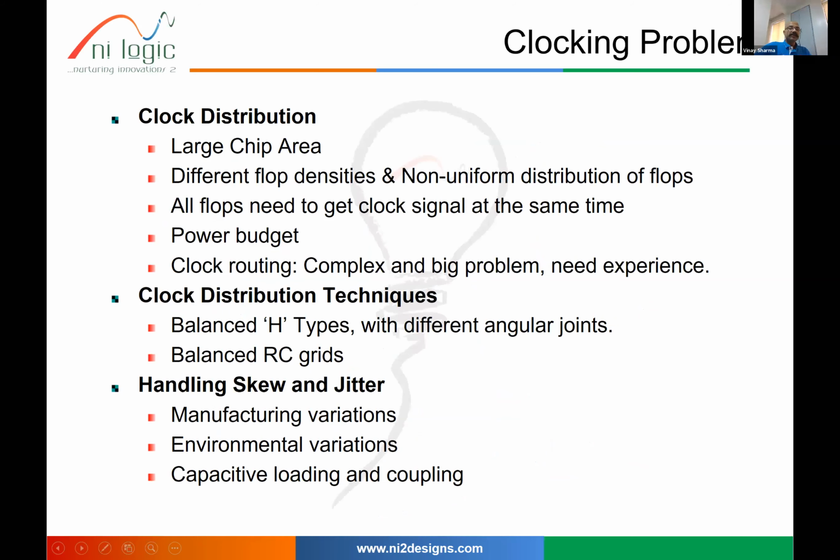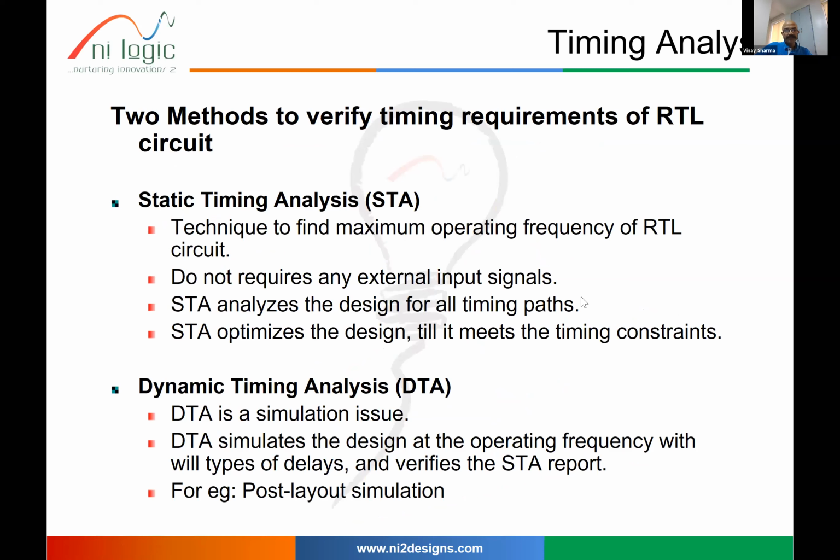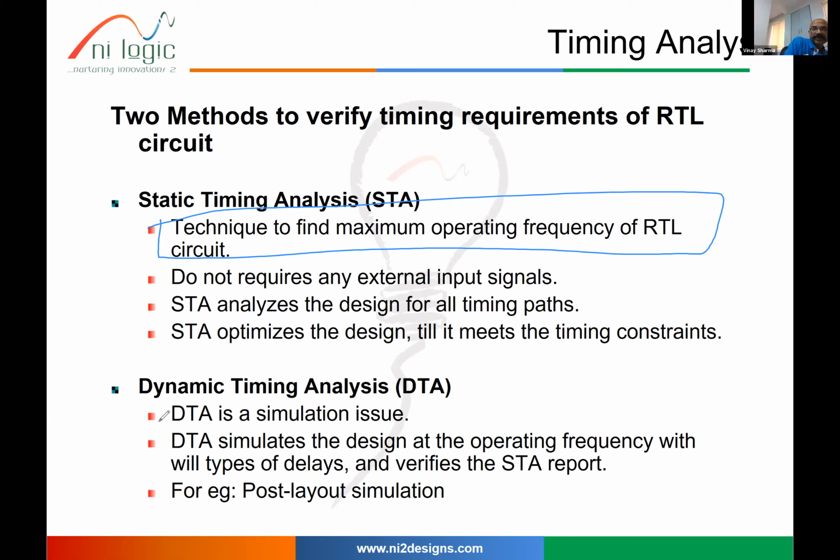Okay. So there are two types of analysis methods. One is STA and another is DTA. Static timing analysis is a technique in which you identify the maximum operating frequency in a given circuit. Whereas in dynamic timing analysis, you simulate the design at that given frequency and verify that it will work nicely.